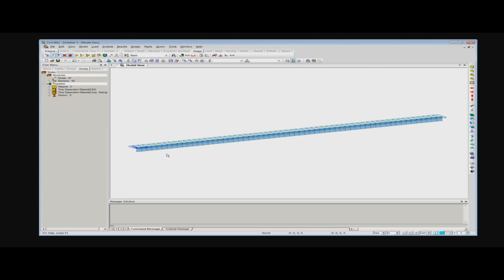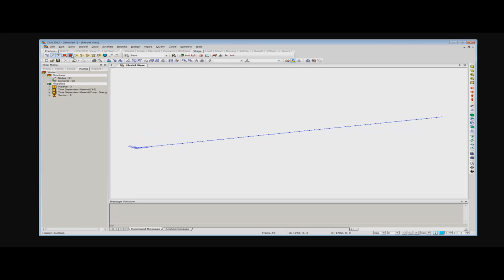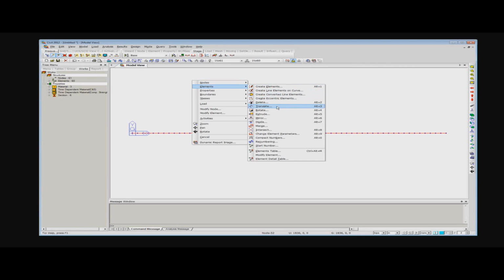Okay, so now what I'm going to do, I need to translate these elements. So if I go to the top view, here you can click the hidden view, so it goes from the hidden to the 3D. So here's your section, and you can turn this on, turn it off. So anyway, go to the top view, and then selecting entirely all elements, and then translate them.